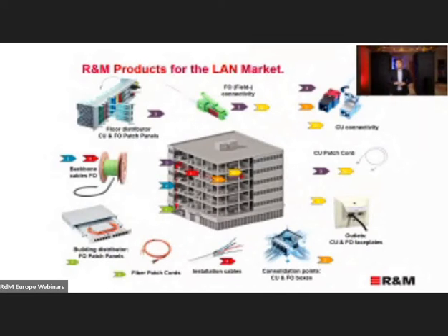Typical design of today's building is that the backbone is made based on the fiber optic cable, and the horizontal cabling is, of course, based on copper. And in fiber optic, there are no limits, let's say, so any application is possible to run. On the copper part, it depends on the category of the components which will be selected. There will be 1 gigabit, 2.5 gigabits, 5 gigabits, 10 gigabits, 25, and 40. Yes, even 25 and 40 gigabits today is possible to run just on single twisted copper cable. And more on that I will tell later today.